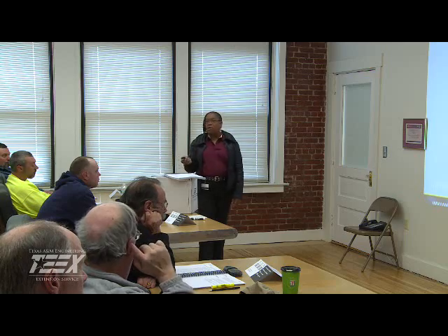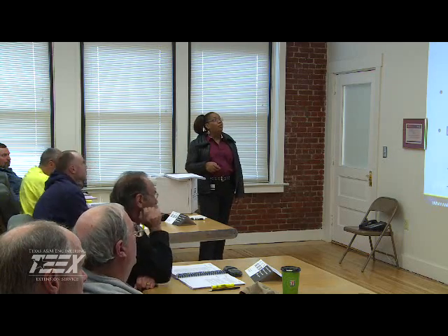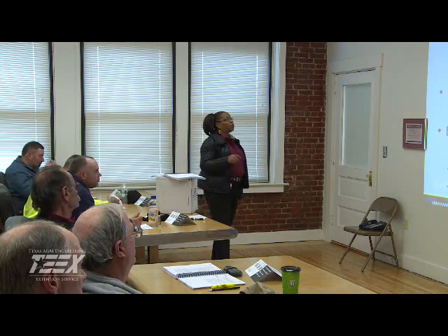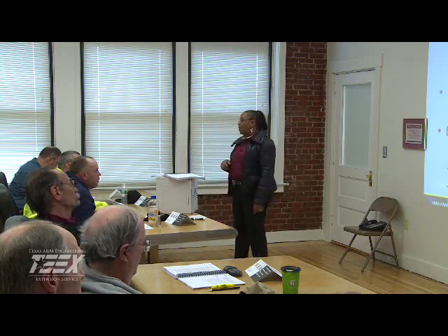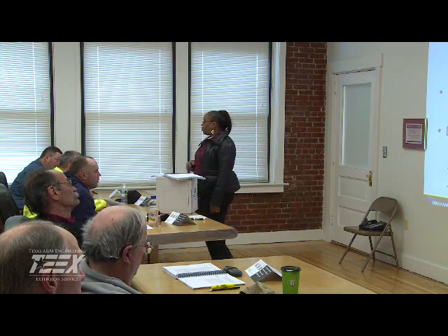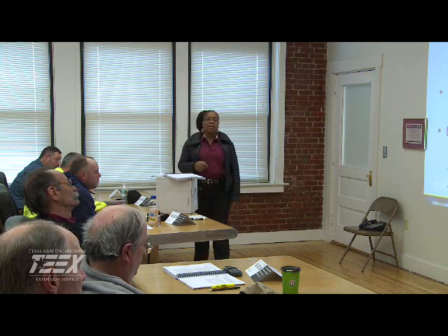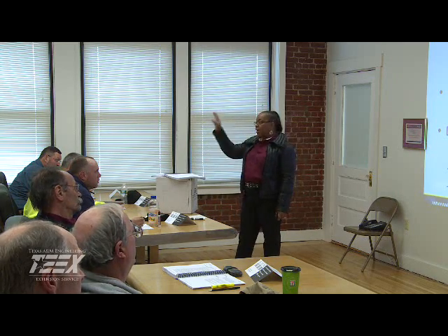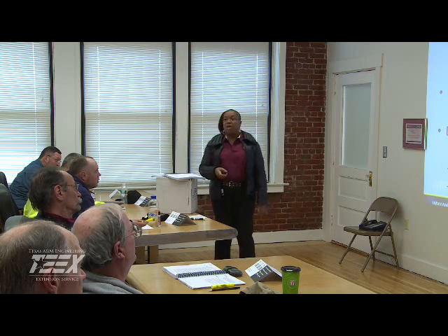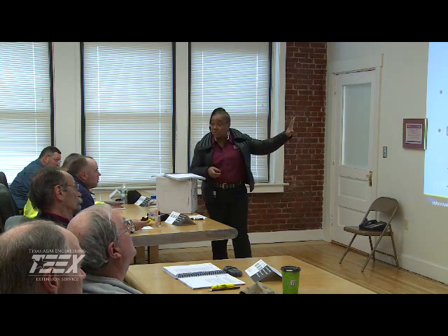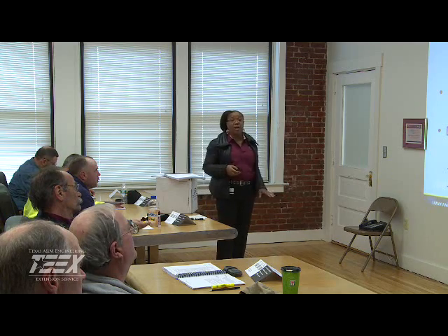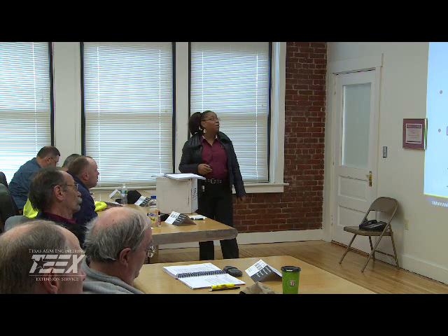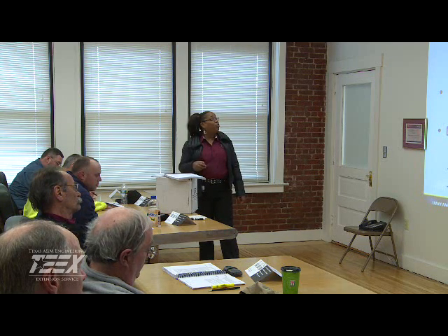All right, for compliance, source water protection, first line of defense. In other words, when we pull those samples from the distribution system, if they come back positive, what the new coliform rule says is, not only are we going back and testing the distribution system, you're also going to whatever source is in production on that particular day, and guess what you're doing? You're pulling samples from those sources also. You want to make sure as far as source water protection, there's no source of contamination within 50 feet of a well. Absolutely nothing.